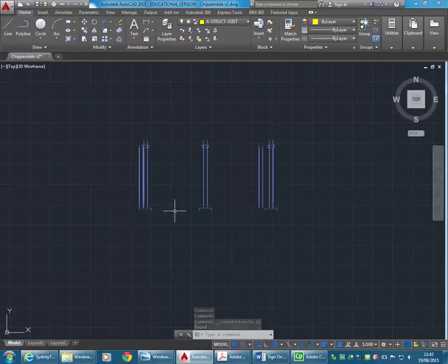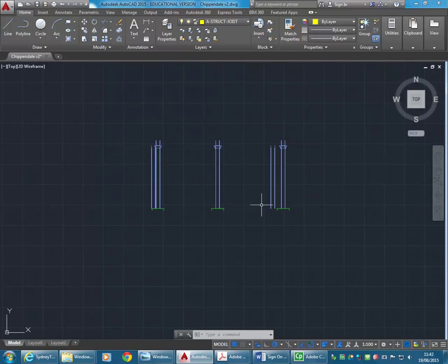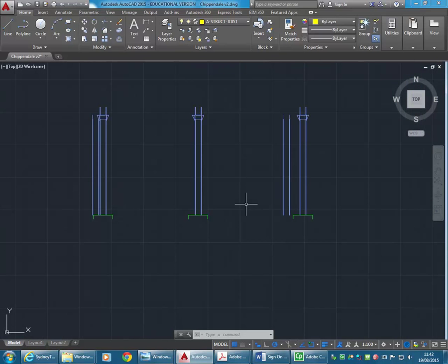We've got the base that just needs to be removed, and so instead of making a new block, I'm going to simply select all of those things that are blocks and explode them. Then just select left to right and remove those base elements. Remember, I measured to the bottom of those, so we need to bring these up 425 minus 150, which is 275. So we stretch,